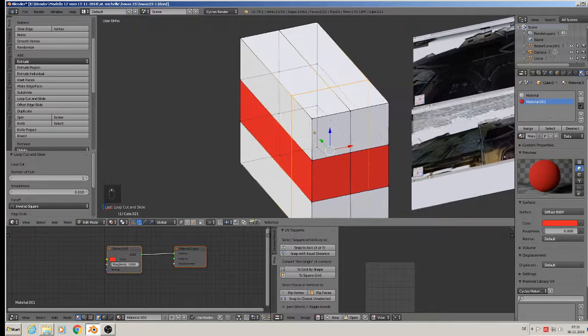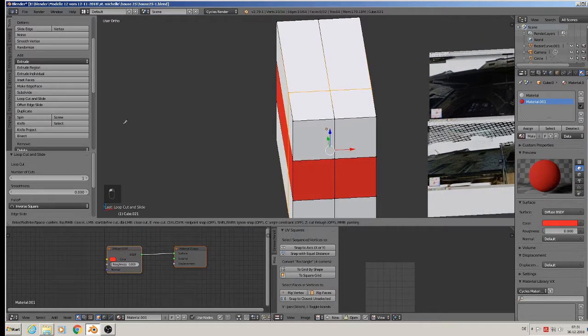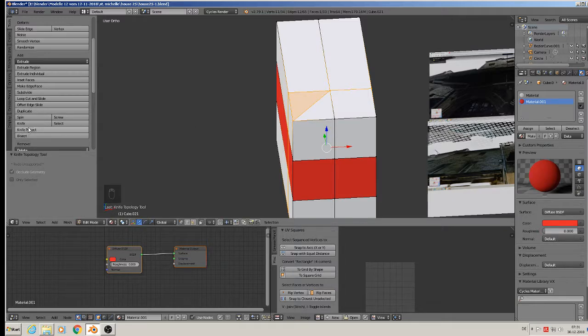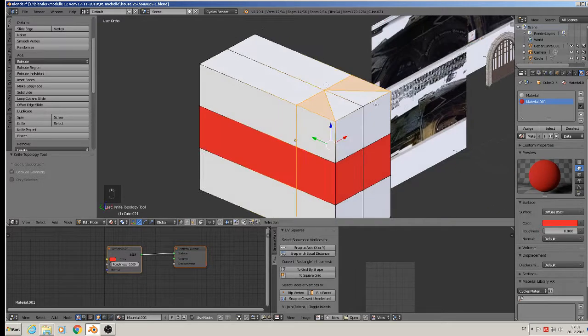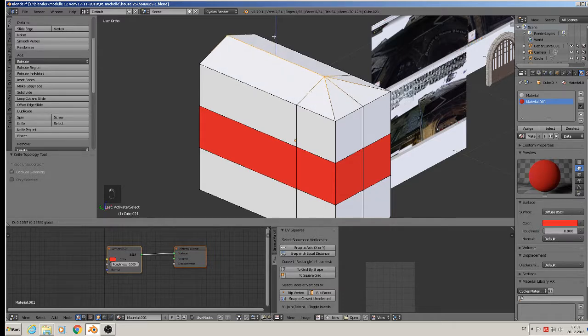Then we have to disable background selection, take a knife, and go from here till there, cut with spacebar, spacebar. Now we can bring up that one here, and we have that roof type there.